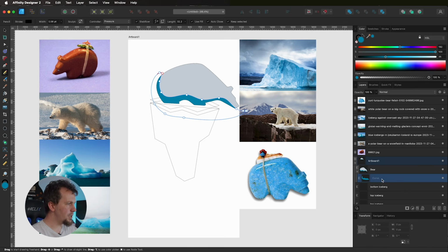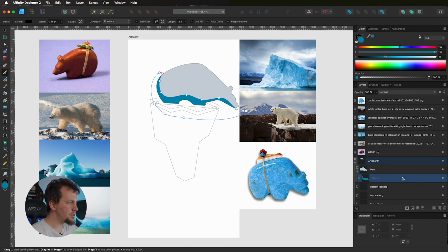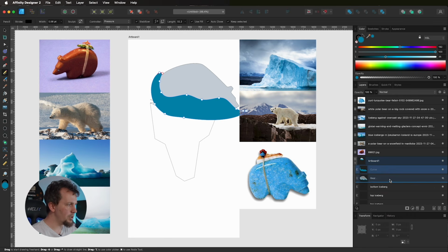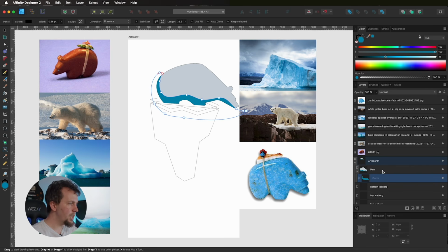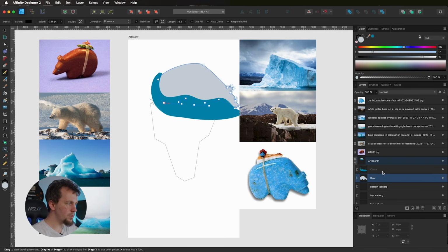You can see if I drag this shape off in the layer stack, we'll just drag it off the bear. The entire shape is quite big, but because we drew it while we had insert inside active, it's going to clip it to that bear. You can really clip anything to any shape in the layer stack. All you have to do is drag the shape onto whatever shape you want to clip to. So if we drag it onto the bear here and drop it, you can see that they basically become grouped. And if I do anything with the bear, like move it around, it'll bring that curve with it, since the curve is now a child of the bear. There are a couple of different ways to clip things.